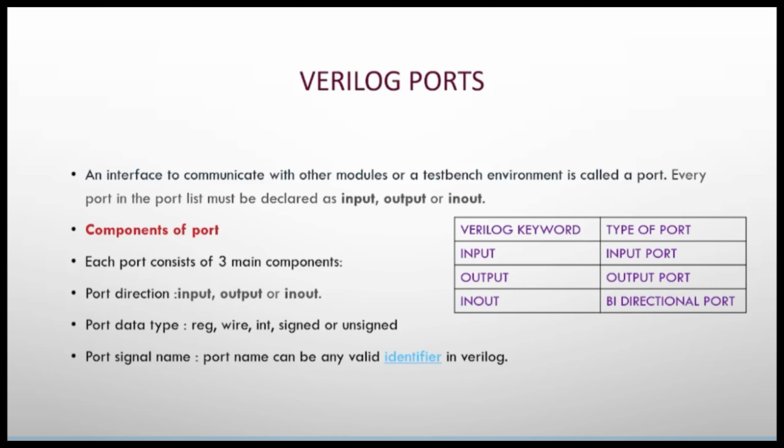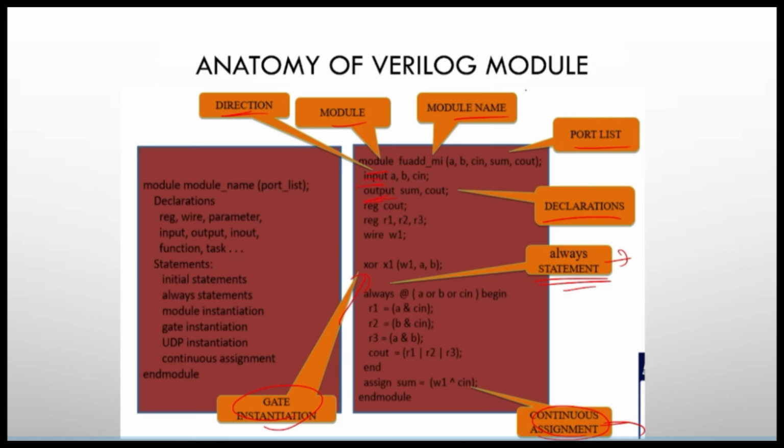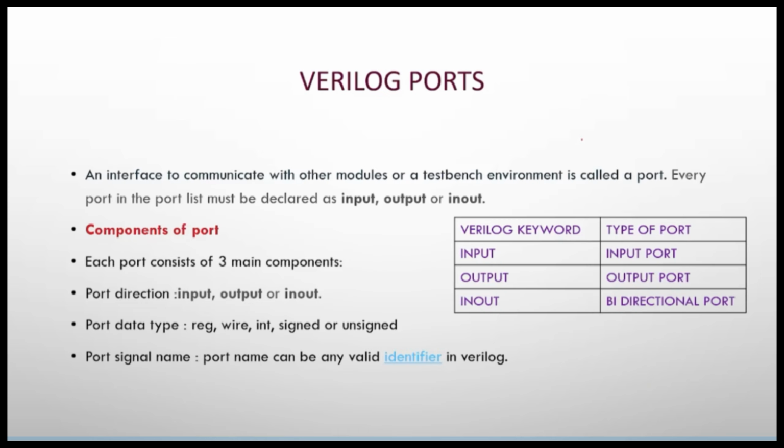So now going into the second concept in the module, you have seen module name and instantiation. Now coming to the ports list. So what are the ports? You already know about the ports. Basically when you are designing anything, it will mostly have two ports. In Verilog you have three ports. Mostly you will be using input and output. You also have another direction which is inout here.